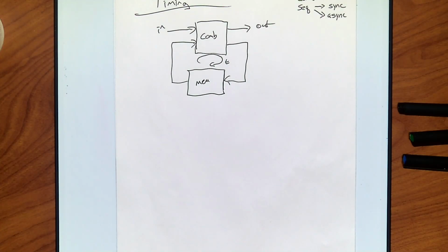That input and output automatically becomes your events list. If you have anything that has an at sign after it in a command, you are specifying an event list. You're telling it what events are crucial, what's going to drive that function.